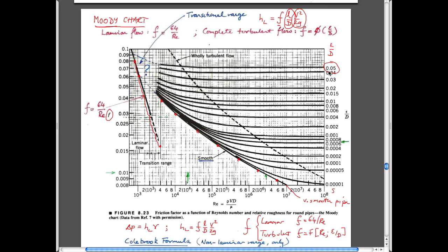And if you did the experiments with this particular roughness, then by changing the Reynolds number, you'd end up with a whole bunch of different results, which would give you the value for this particular roughness. And so the idea is now you just work your way through the rest of the roughnesses and you can fill out this whole diagram. Don't need to know anything about solutions for flow in pipes. In fact, you can't get those solutions for flow in pipes from an analytical way. You just do it by experimentation, and then you hope to be able to apply this for all the conditions that you could imagine in terms of relative roughness that you have for different pipes and different flow regimes. So that's it.